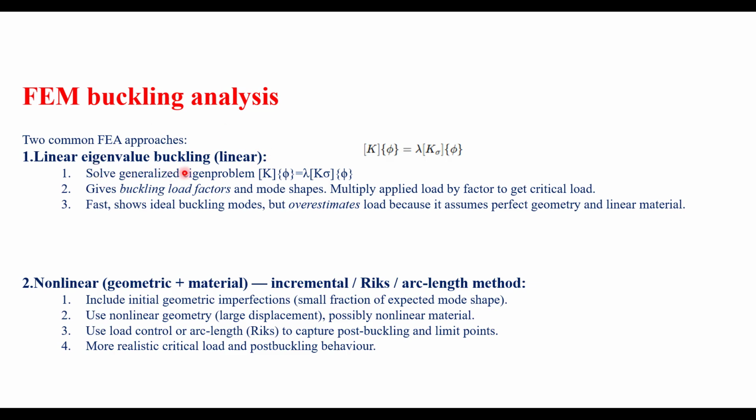Okay, in short, this is the formula we use. What exactly it does is it gives us the buckling load factor and also the mode shapes. So we can multiply the applied load by the buckling factor, which gives us the critical load. For example, assume you have the model. You can simply apply the unit load and then get the buckling load factor, that is the exact critical load. I'll anyway showcase that in the live demo.